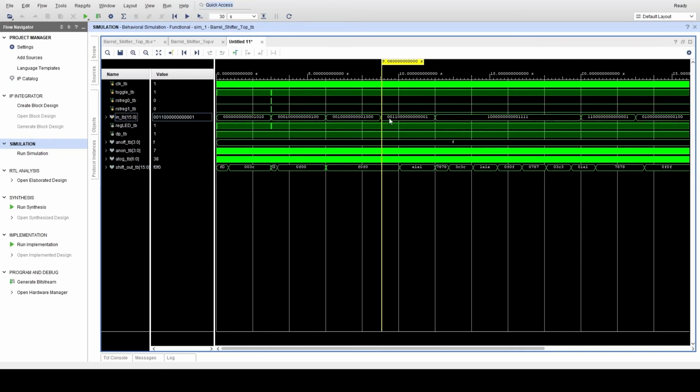So that works. And then this input value is manual mode, no load, rotate left with a bypass value of 0001, which is 1. We are rotating left by 1 bit, and as you can see here, F0 rotated left is E1, which is what we expected.